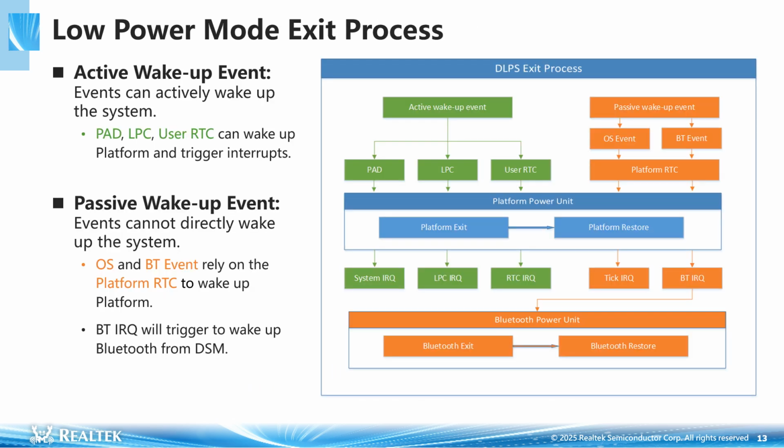The low power mode exit process is shown in the right figure. Active wake-up events are events capable of directly waking up the system. They include PAD, LPC, and user RTC events. These events have the ability to wake up the platform and trigger interrupts.